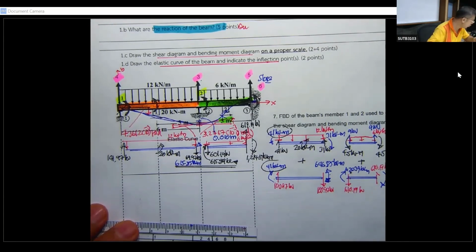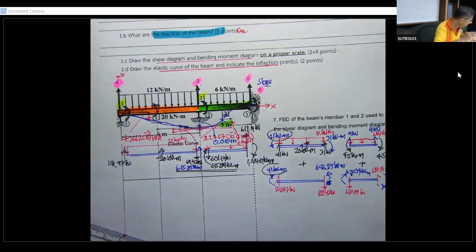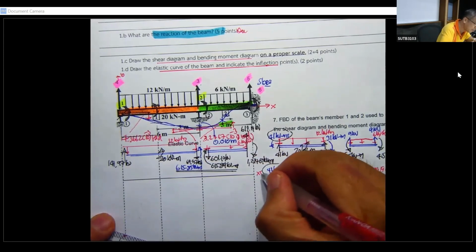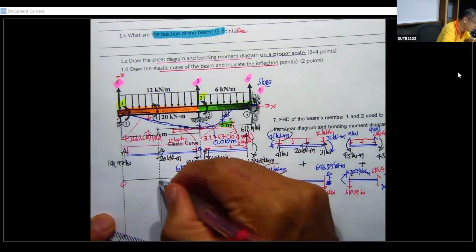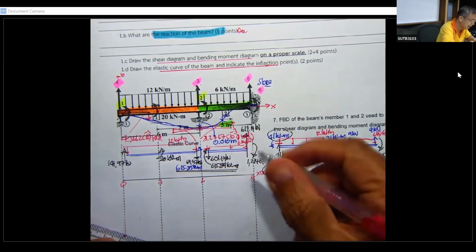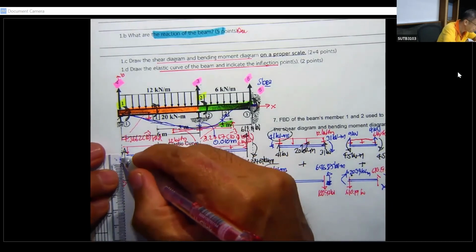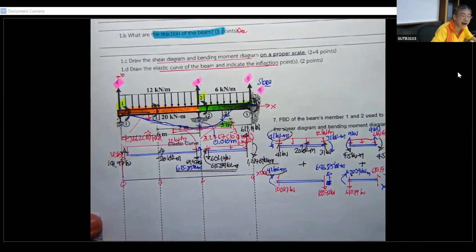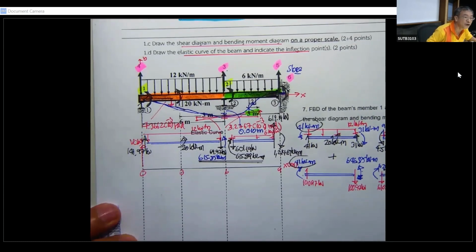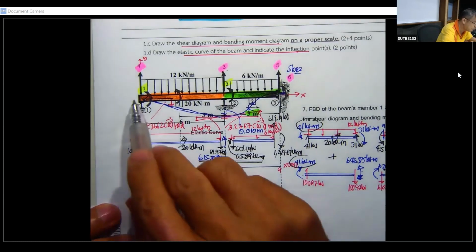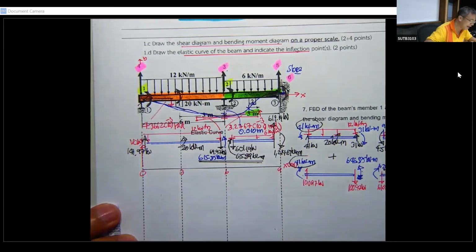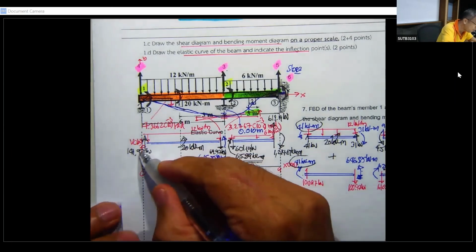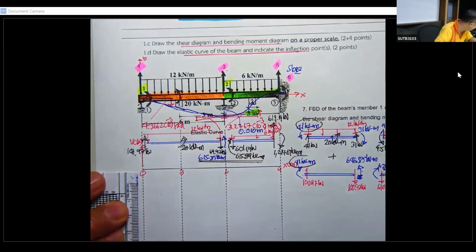Okay, if you prefer to draw it, just make it like this. I put everything like this, so don't worry. This is going to be x in meters: 0, 3, 6, 9, and then put this one into V in kilonewton. And let's draw the shear diagram. First, we move from the left to the right again, and then we have this one for 141.97.